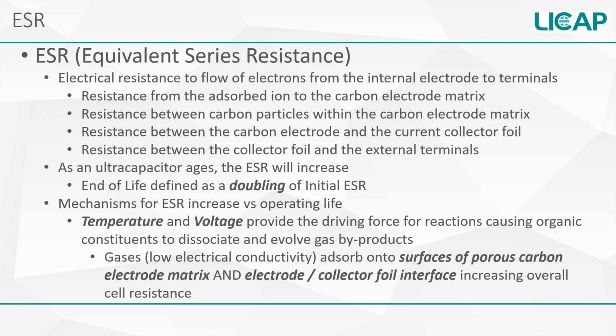ESR, or equivalent series resistance, is the electrical resistance to the flow of electrons from the internal electrodes to the external terminals. It's the net sum of resistances from multiple interfaces, which we will explore in the next slide. As an ultracapacitor cell ages, the ESR increases, creating higher average temperatures and an acceleration of further property degradation.